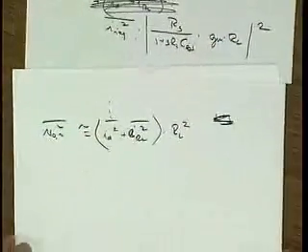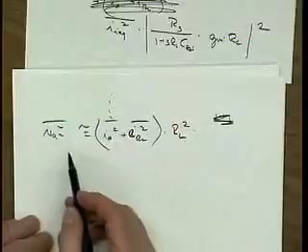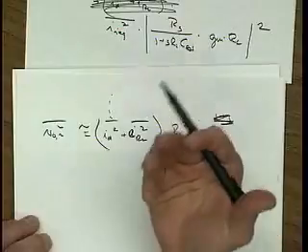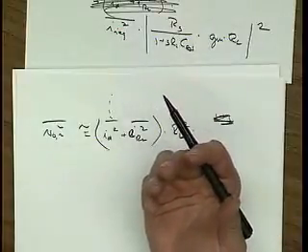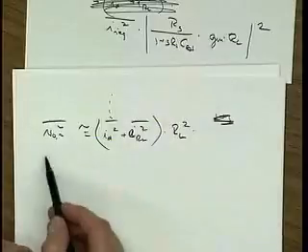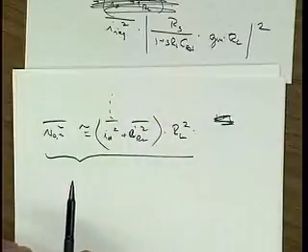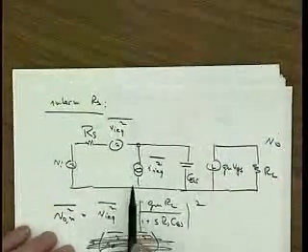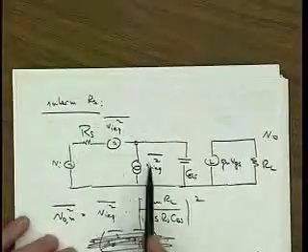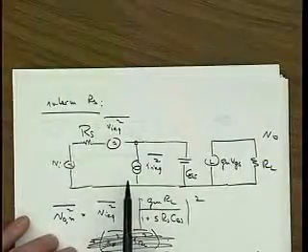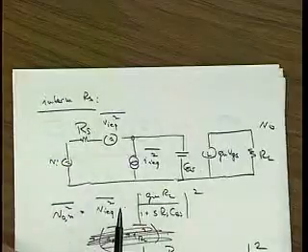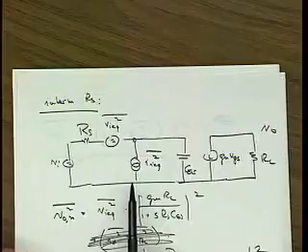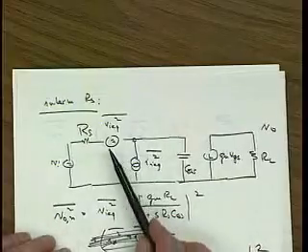Okay. Now, if you go and compare this to the analysis of the circuit that we had done before, without using these input equivalent noise sources, you will find that this result here is not exactly correct. And the reason is that when we use this representation, all of the noise from the circuit is already modeled by VIEQ, and all of the noise is also modeled by IIEQ. They just enter the circuit in different ways as voltages and currents.